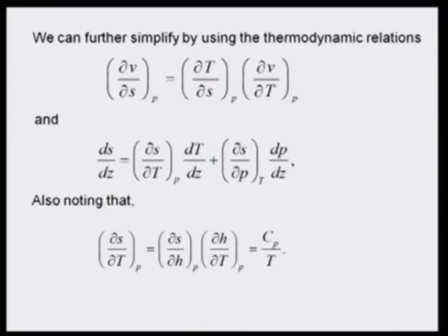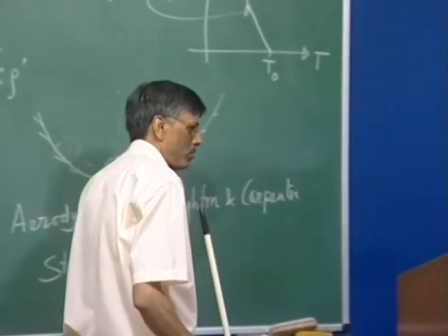Okay. Now, in this quantity I have this ∂S/∂T. I could write ∂S/∂T in this particular fashion: ∂S/∂H and ∂H/∂T at constant pressure. H is what? Specific enthalpy, right, specific enthalpy. So, that part, H is what? Cp into T. So this quantity is Cp and this quantity is 1 upon T. So we are doing all the tricks that we have learnt in our equilibrium thermodynamics course.